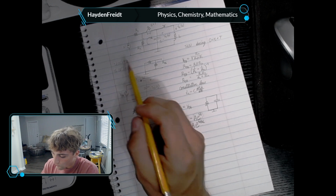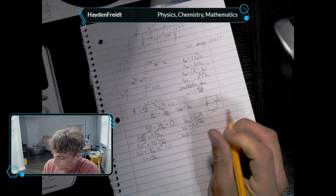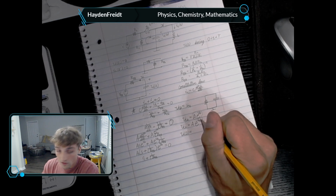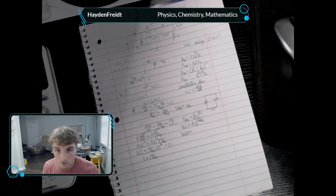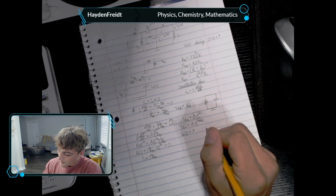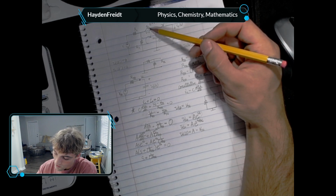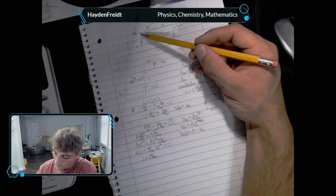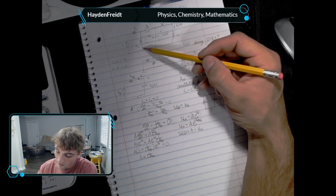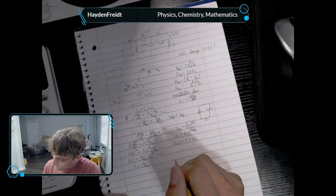VCH, just moments before. Okay, so it's just going to be VC. We're just going to say VC of 0 equals our Thevenin voltage. If you plug in 0 here, you're going to have 0 in the exponent, and then what is a variable to the power of 0? It's just 1. So if that's 1, we simply have VC of 0 equals A, and then that's just going to equal V, our Thevenin voltage. Because think about it, as soon as this closes, our voltage divider is going to give us the voltage across this resistor, which we defined as our Thevenin voltage. So our Thevenin voltage, this being in parallel with our capacitor, is going to be the same voltage across the capacitor. That's how. Okay, so our final solution is going to look something like this.